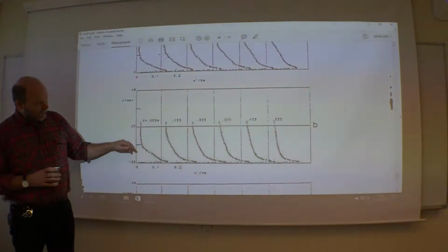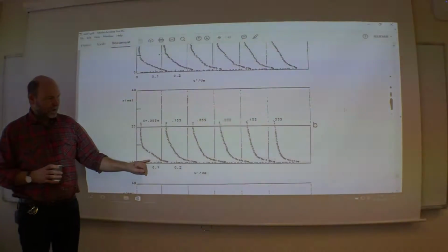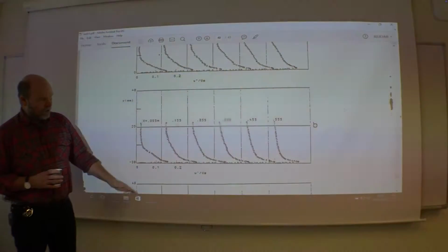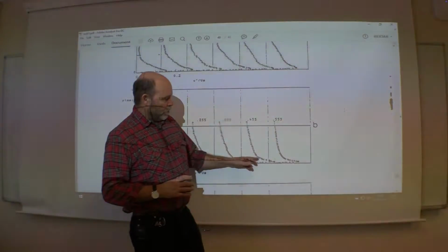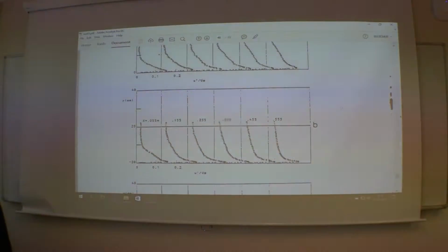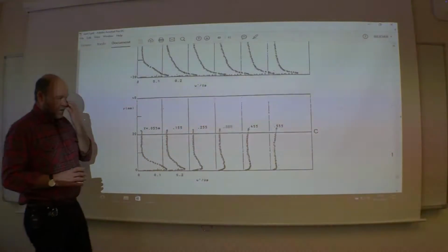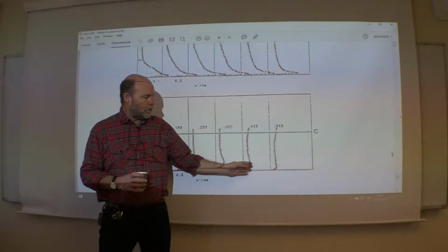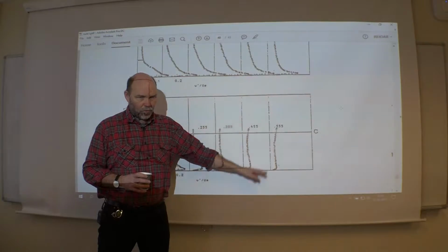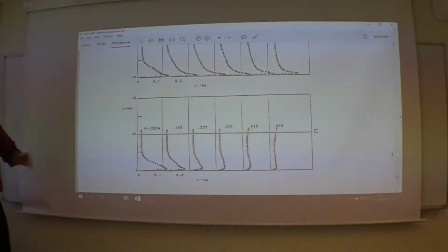So then this region where you have very high turbulent activity is sort of squeezed more and more towards the wall. While on the suction side, you see they are getting more and more laminar, tending more and more towards zero. So less and less turbulent activity. The damping here is quite strong.